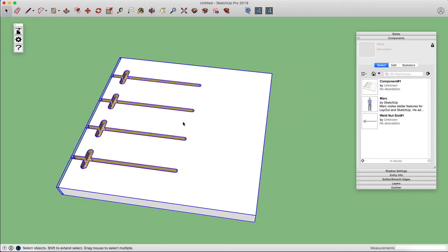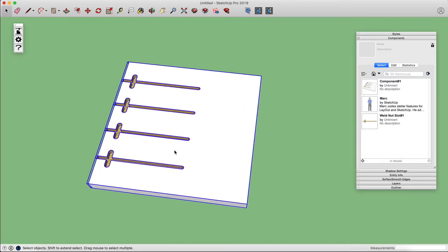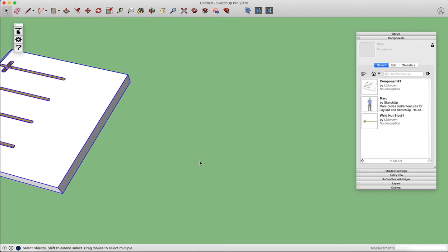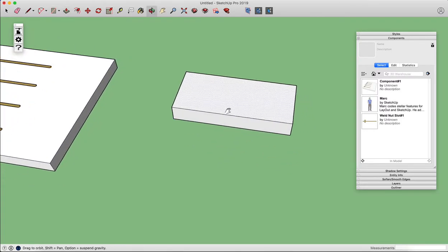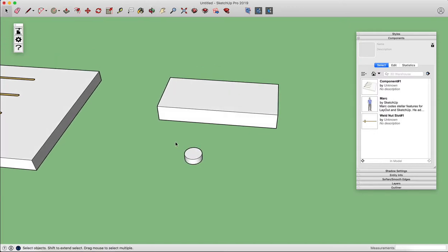And so we're going to provide some pre-made connectors, like these weld nut slots and other common fasteners. But if you want to create your own, I'll do a more in-depth tutorial, but basically the way it works is this. SketchUp has this notion of components that can cut holes in other parts in SketchUp. So I'm going to make a very simple component like this. We'll make this a circle.